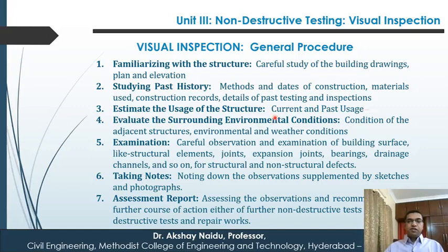Estimate the use of the structure, current and past usage. Whether the structure was used as per the design estimations or it was overused or underused. This has to be determined. Evaluate the surrounding environmental conditions, conditions of the adjacent structures, environmental and weather conditions.